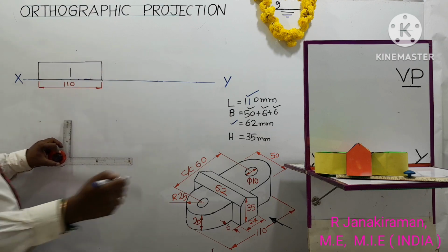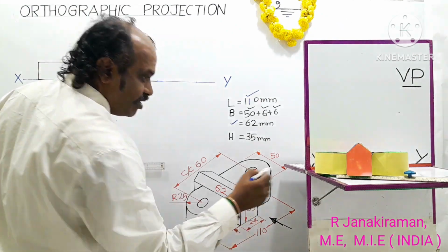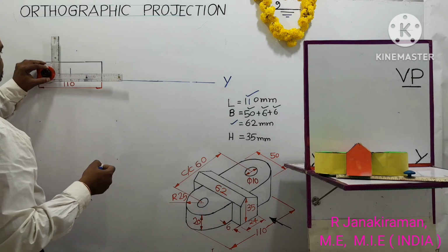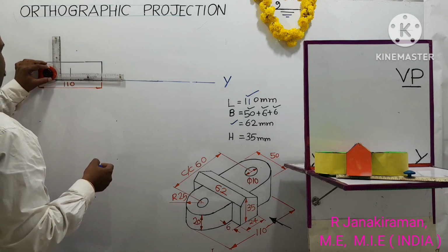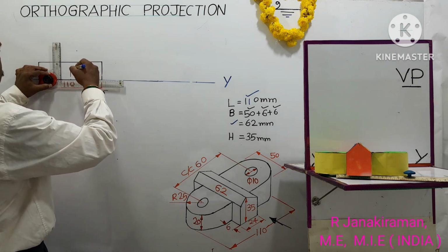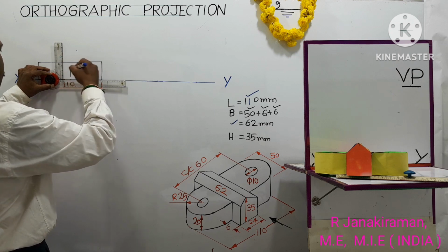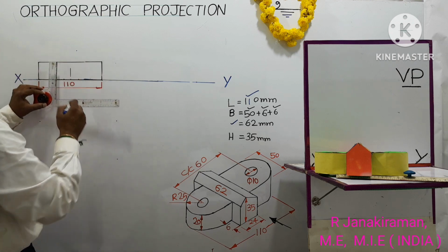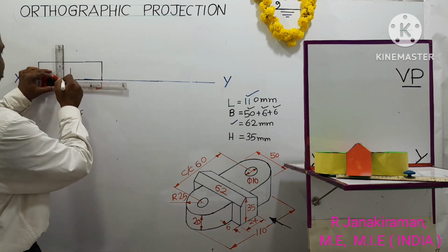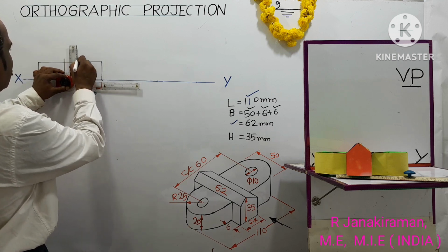Okay. Now the red color portion distance is given as 24 mm, from this point to this point. Okay, here to here is given as 24. 24 divided by 2 will be 12 mm on both the sides. There you locate points. There you draw a vertical line using the HB pencil. All these works are carried out by HB pencil, which appears to be dark.